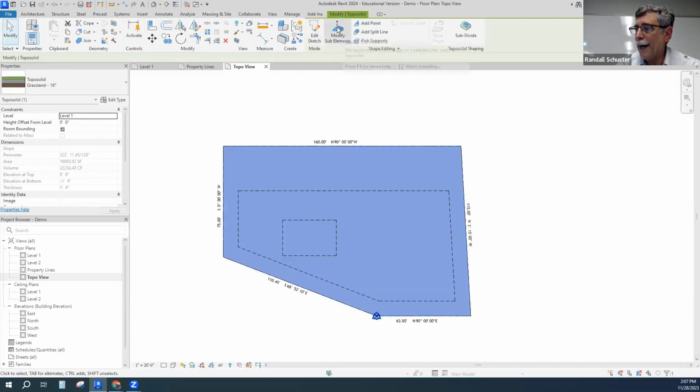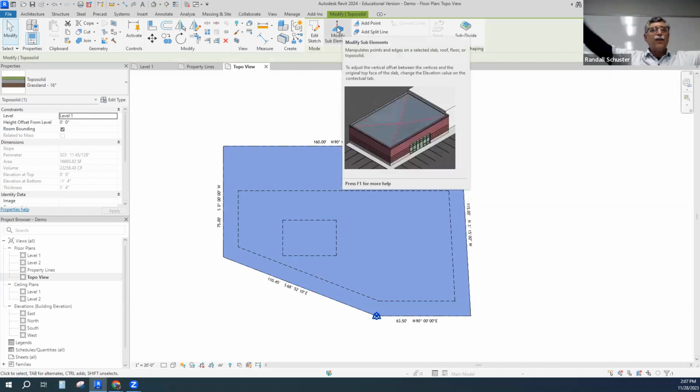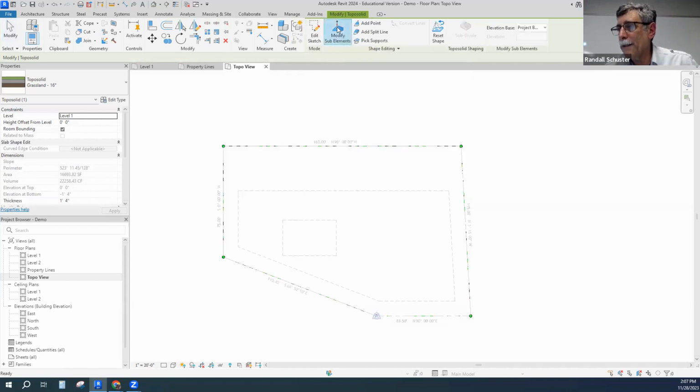And now I'm going to modify the sub elements. Right now, those are all put at 0, 0. And I know that some of these have an elevation. So modify the sub elements. This one, if I click on it, it tells me it's at 0. It's hard to see, but it's there, 0. So that one's correct. Let me go click on the next one. It's also at 0. And what should that one have been? 6. And I'm already in it, but I'll put feet.